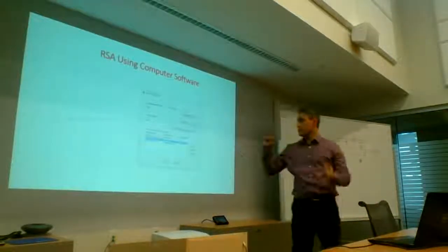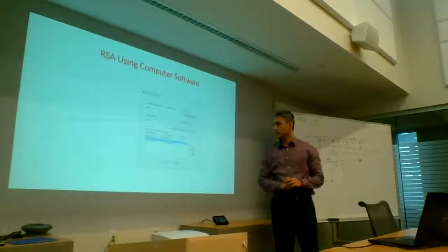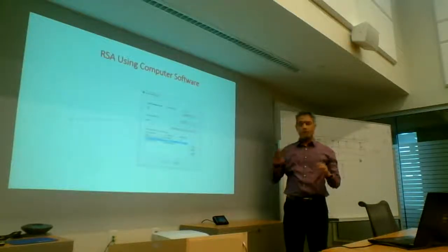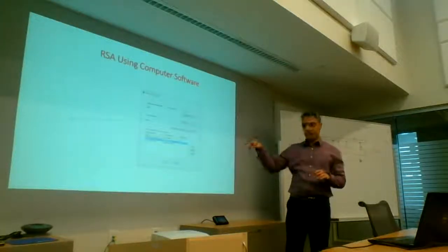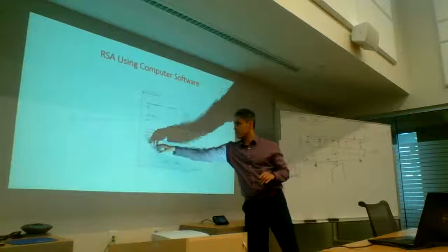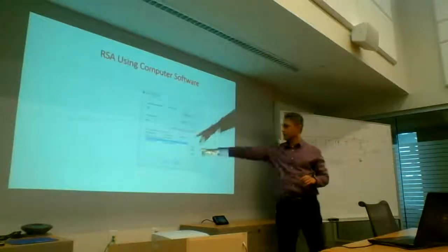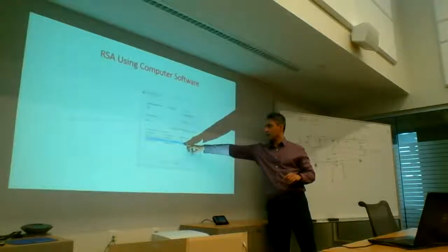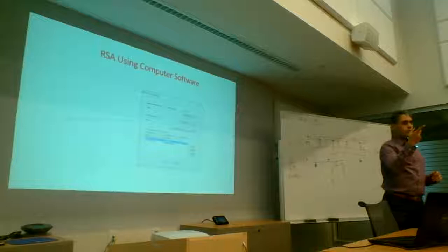And this is where now my dead plus seismic combination is happening. If you look, the code says you have to use 1.25 times the dead load plus your seismic. So the seismic is this response spectrum, which is 1 longitudinal plus 0.3 transverse with a factor of 1, and this is 1.25 on the dead load. You also have to use 0.8.